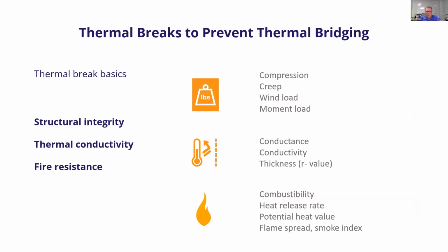So lastly, the 3 main important takeaways from this, from my perspective, are when we're using thermal breaks to reduce heat loss and to improve energy efficiency and bring down energy demand, we just need to pay attention to structural integrity, compression, creep, thermal conductivity, obviously, because that's the whole point. And lastly, fire resistance, which isn't talked about enough, in my opinion.